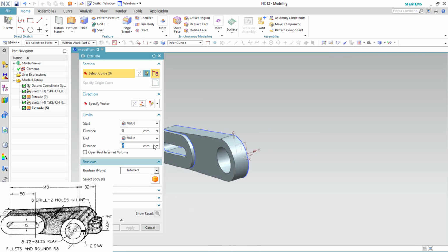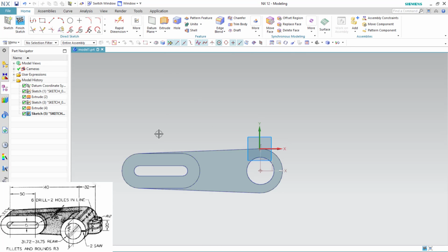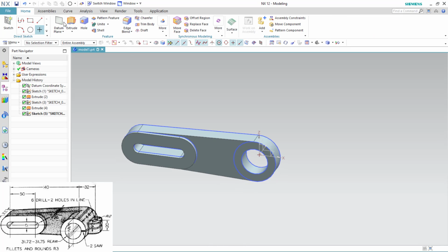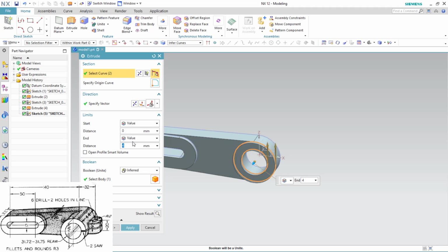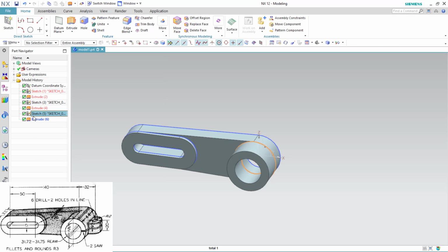Yeah. So next thing is to deal with the side boss. So again, you can select this face as a reference. Sketch. These two done. Here one more. Yeah. I should extrude it. The distance is total 22. So 22 plus 22 is 44. Minus 18 will be the value. Up to that particular value I had extruded. No, up to 18. Yeah. Sketches, you can hide it.